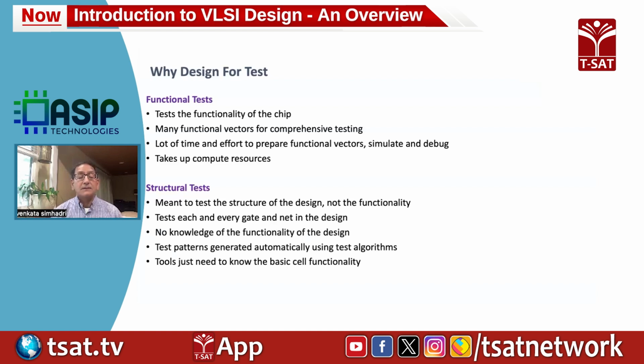It takes compute resources, but people will still need to do some functionality test before they release it to production. And then there is another form of test, for the structural defects. Let's say you're taking your gate level netlist and converting that into a physical layout.